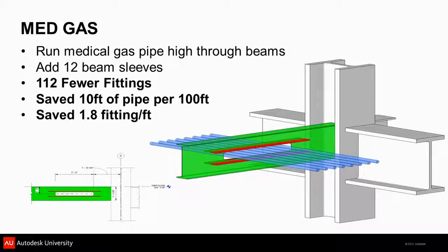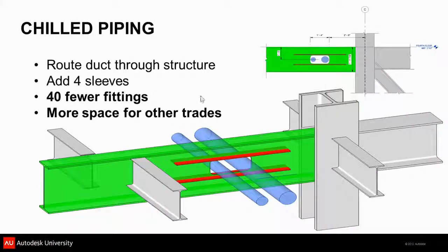So here's what I think of when I think about penetrating steel. I want to look for typically pressure systems that are flat. I like to have my openings so they're repetitive, because the engineer does need to design the solution. And if I'm not the structural engineer of record and I'm working construction side, I will basically write this up as an RFI and we'll give them a mock-up like this. And we've actually run the engineering calcs and we know this works before we send the RFI through.